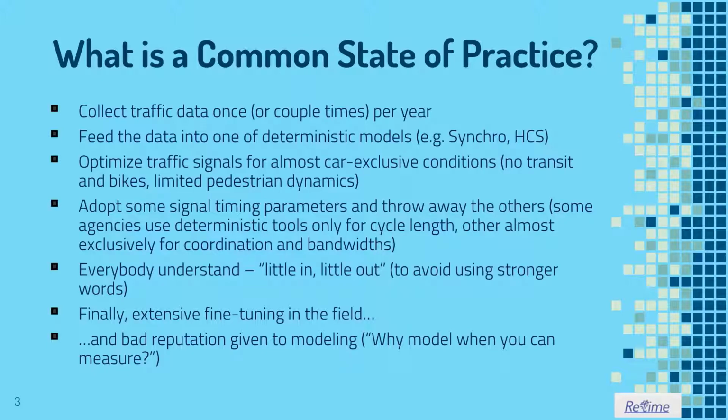We are not considering all of these multimodal options, which we claim are important for us. And then what happens is that some of the agencies are really going to use these tools just for some types of signal timing parameters. I know an agency that says, we are not using Synchro or similar tools for all of the signal timings. We'll just do recommended cycle length, or others will solely rely on these tools for the bandwidth optimization and to adjust their bandwidth. And as we say, if you put a little bit in, you'll get a little bit out.